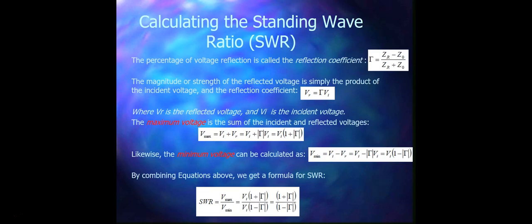You can use a capacitor, which can be added to cancel an unwanted inductive reactance. You can also use an inductor, which can be added to cancel an unwanted capacitive reactance. All these solutions can be used to avoid the impedance mismatch.